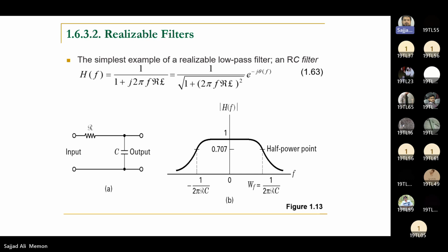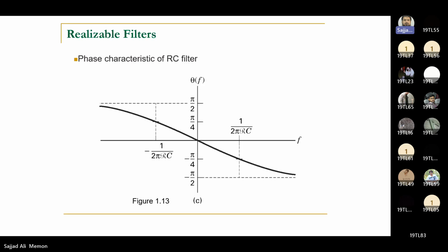This is the actual frequency where we would like to drop the cutoff, but the power becomes zero only after a point where a few extra frequencies are already added. These are impurities, which will cause the aliasing effect in the filter, because we allow more frequencies than we wanted to. That is the clear difference between realizable filters and ideal filters.